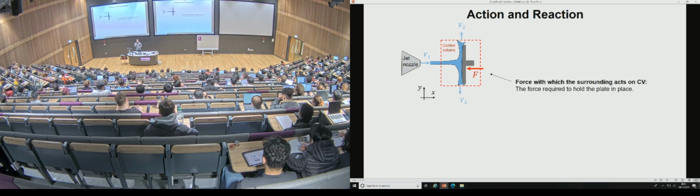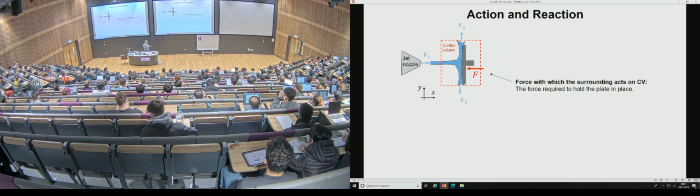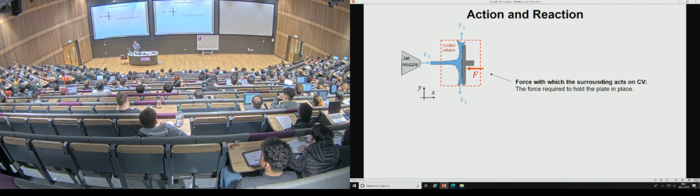And in order to do that, we have to introduce the concept of Newton's third law, so the action-reaction. And this is where understanding what is included in the control volume and what isn't becomes really central. So if inside your control volume you have a physical object which is bringing the flow to a halt, then there's a force that is acting on the control volume.